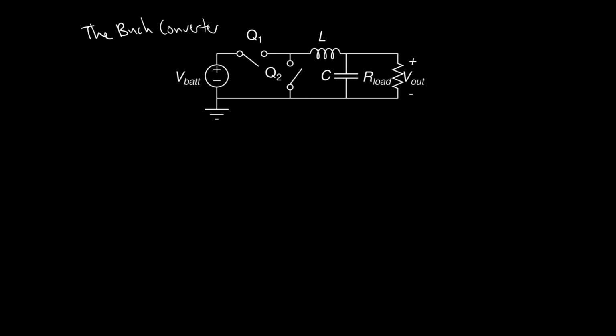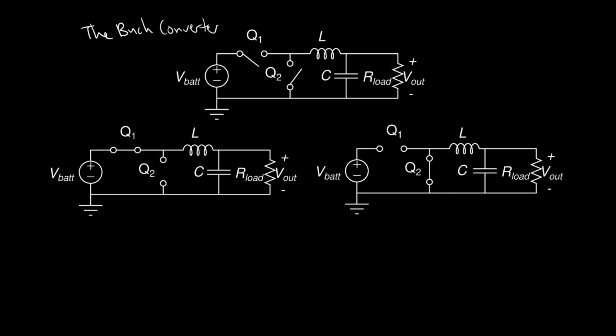We got there, right? We somehow derived a buck converter by thinking about a resistive divider, using a transistor as a switch, and then kind of filtering out the high frequency components, and then adding an extra path for the inductor current to flow. So this was kind of a unique way of deriving a switch mode power supply. Most converters can't really be analyzed in this way. The buck converter is kind of unique in that all we're doing is chopping up a DC voltage, creating an AC waveform with a DC component, and then filtering out the AC components to get a constant output voltage.